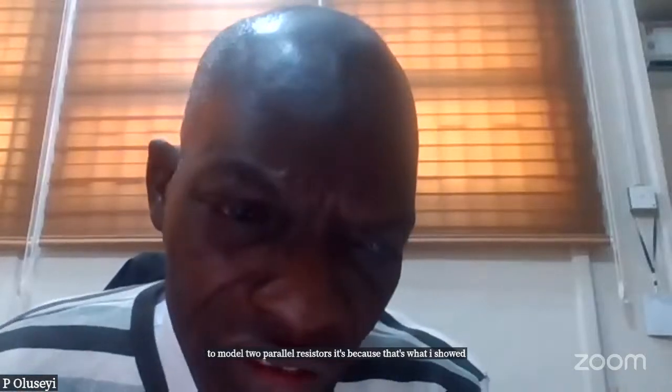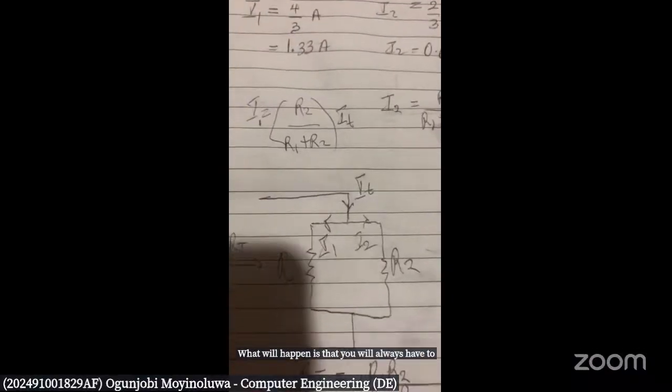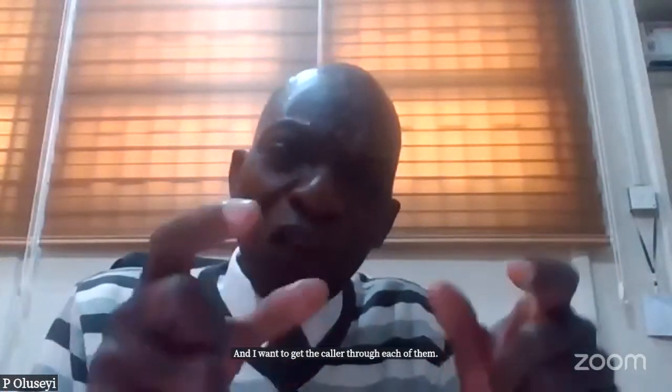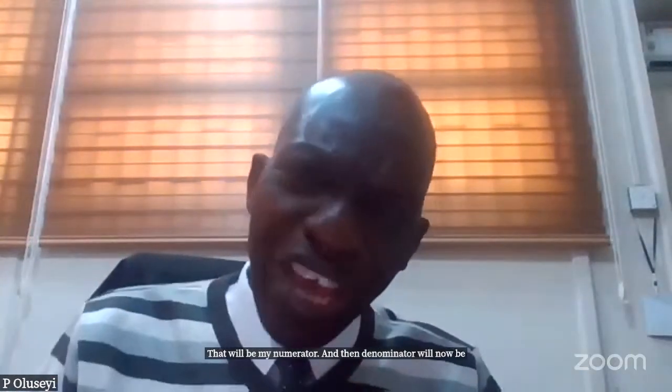It's because that's what I showed in my own explanation. So in the case of three, what will happen is that you will always combine two of them together. If I have R1, R2, R3 as my parallel combination, and I want to get the total, what I will do is R1R2 plus R2R3 plus R1R3, and that will be my numerator. And then the denominator will be R1 plus R2 plus R3.